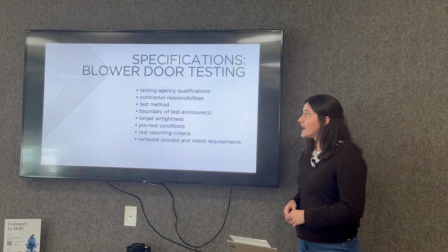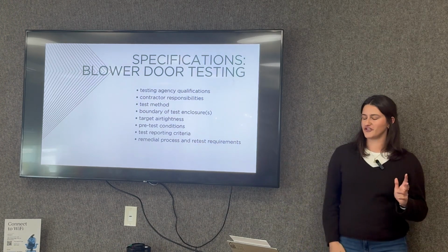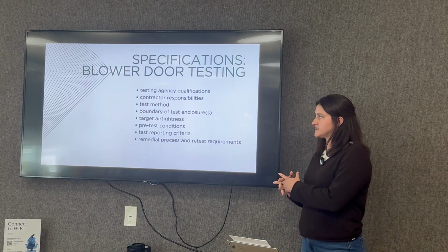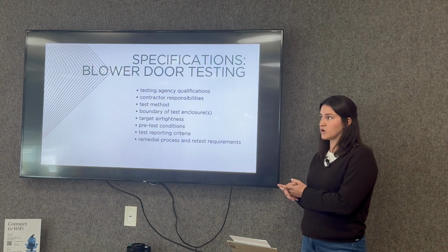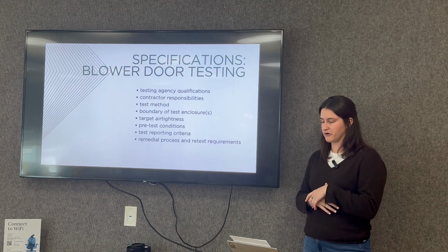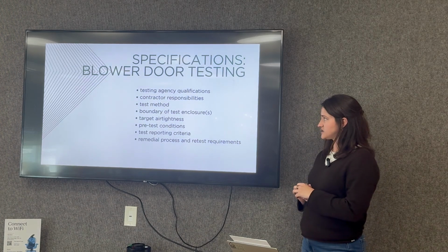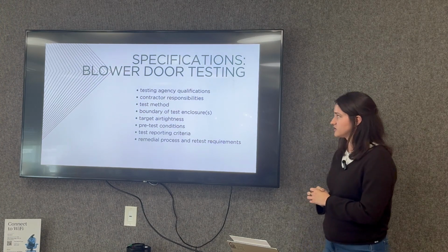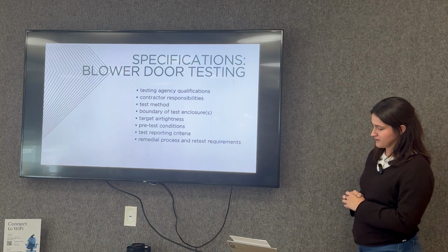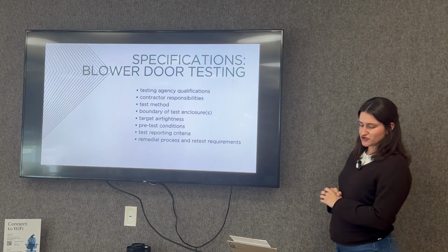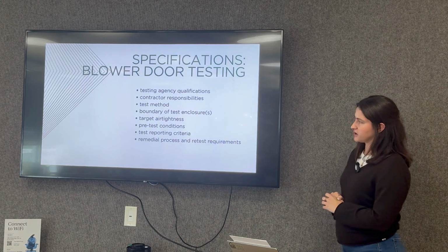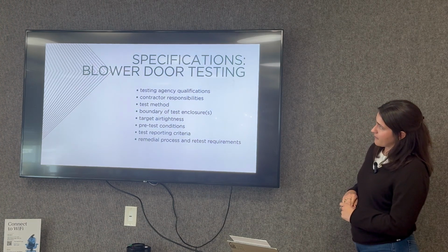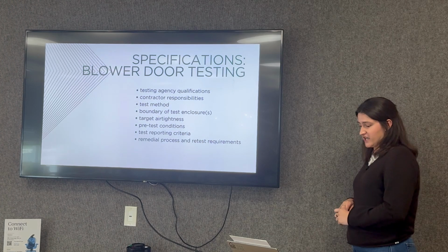So in Georgia, as of today, I say that because I'm not from here, the building code does not require whole building airtightness testing, but in most jurisdictions, it is listed in the building code as one option to show code compliance for your building air barrier. And in order for a testing agency or an engineer to perform the airtightness testing, they need to know the target air leakage rate and also what test standards and method to test underneath. After we discuss Chapter 2, construction, we'll look more into the various building codes and other jurisdictions that give us target air leakage rates.